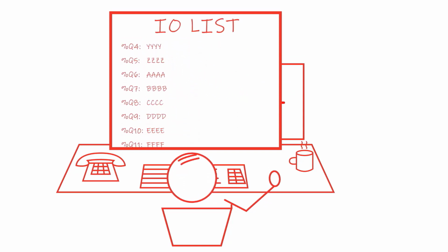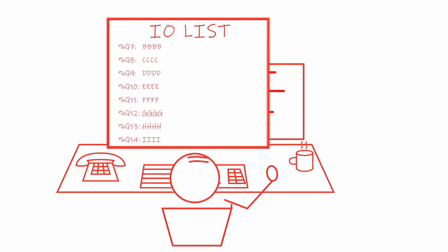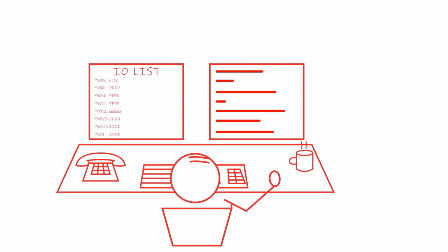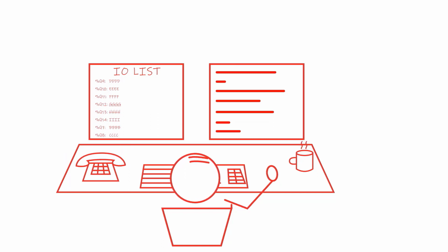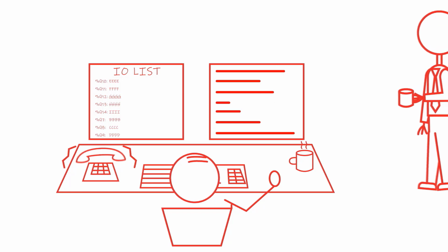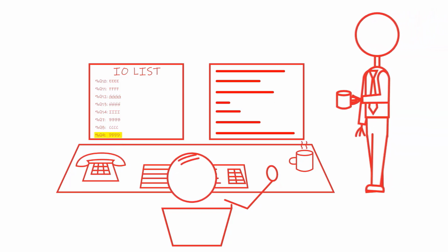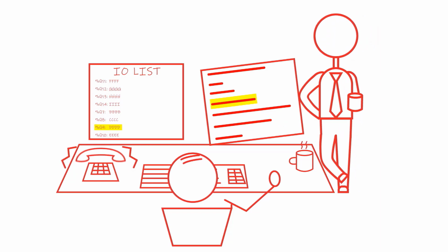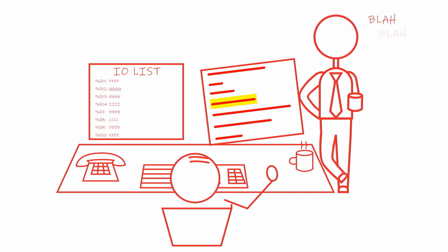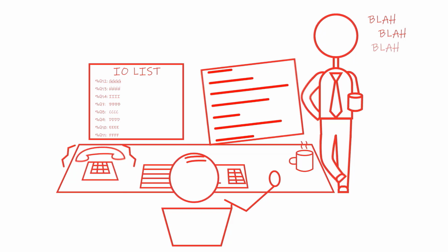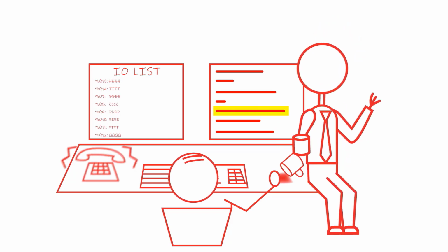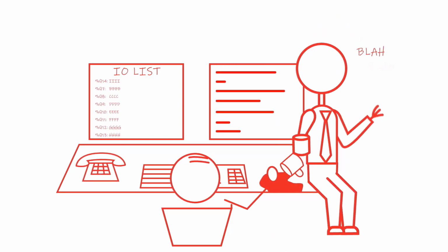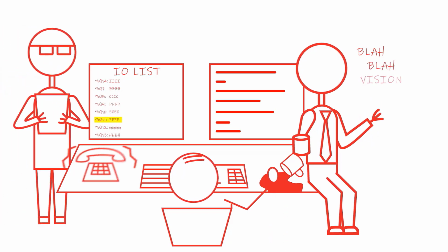Regardless if we use ordinary ladder logic programming or automatically generated code derived from a multi-physics model-based simulator, ultimately, we need some sort of intermediate program to transfer data from the schematics to the PLC code. A traditional method would be to use simple text files or Excel spreadsheets and cross-check each device one by one against the data in the PLC programming tool. This is a time-consuming task and prone to errors as it relies on the dexterity and concentration of the designer/operator working the programming tool.